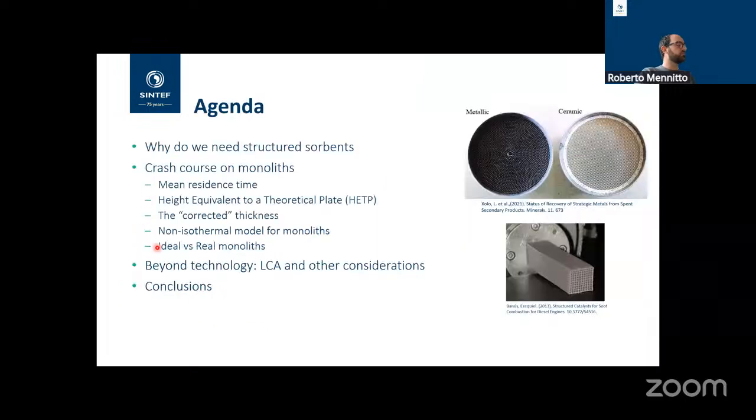The agenda: we will quickly look at why we need structured sorbents in the first place, and then we will deep dive into a short course on what I believe personally are the fundamentals of monoliths, so the mean residence time and the height equivalent of a theoretical plate. Then we will of course look at what happens when we have non-isothermal conditions, a real monolith, and so on. And finally, we will conclude with some thoughts from experience on what happens to monoliths when they go from technology to the real world.